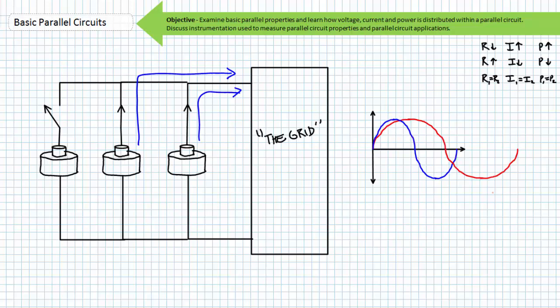The generator could have the correct magnitude and the correct phase shift, but the wrong frequency. At the moment of synchronization, a differential would still exist. Finally, the generator could have the correct magnitude and the correct frequency, but the wrong phase shift. At the moment of synchronization, a voltage differential would exist.